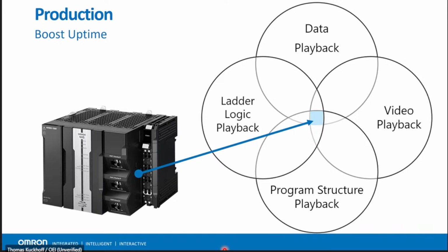again, the power of Sysmac is that the controller is sitting at the nucleus of the architecture. So by having all that unification capability, by having that holistic data, you have the ability to play it all back. You have the ability to have your ladder logic, your video, and your data time synchronized, which is very important when you're trying to find the root cause of a failure or a deviation from what should have happened as shown in a simulation.